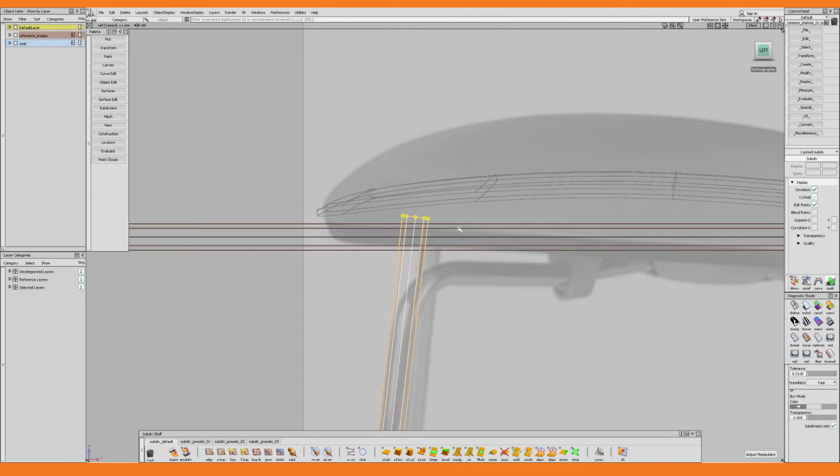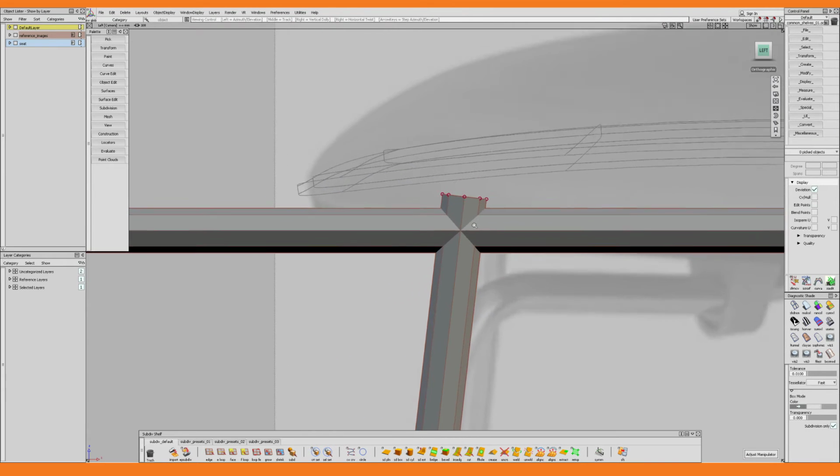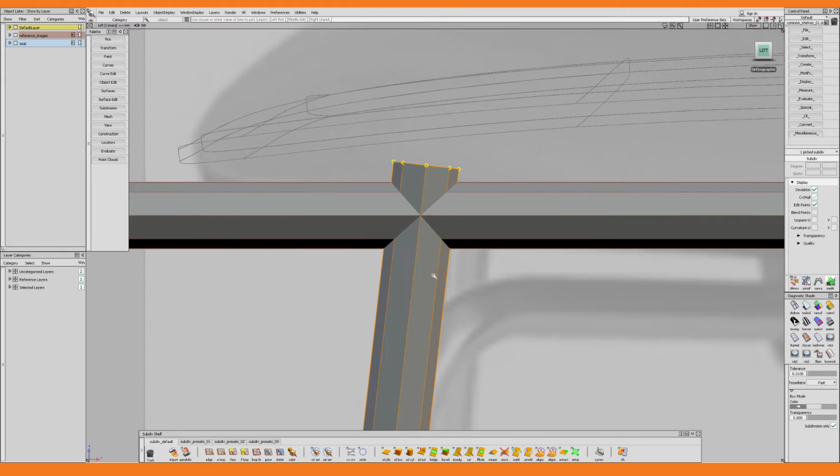place. As of right now, there is no way of unifying these two pieces by way of a Boolean operation, at least not that I know of, so I have to do it the manual way by using the cut tool. So I make a cut on one of the cylinders, and then I make the corresponding cut on the other one.